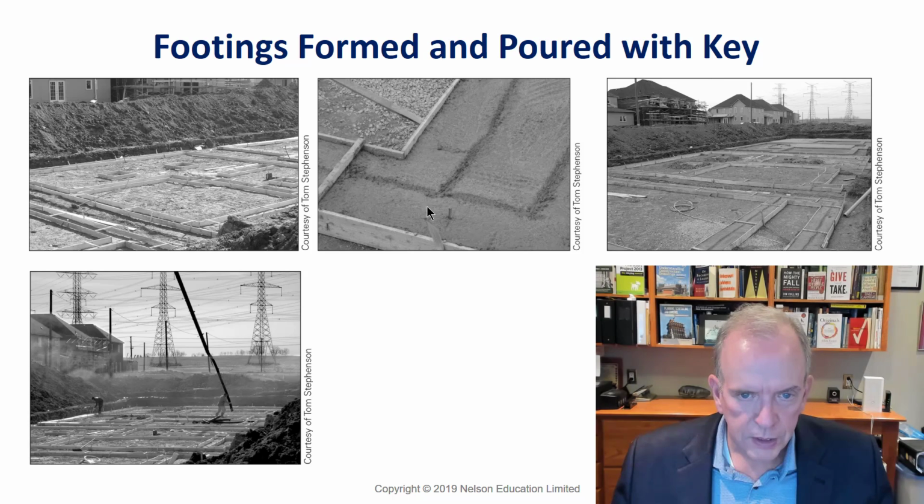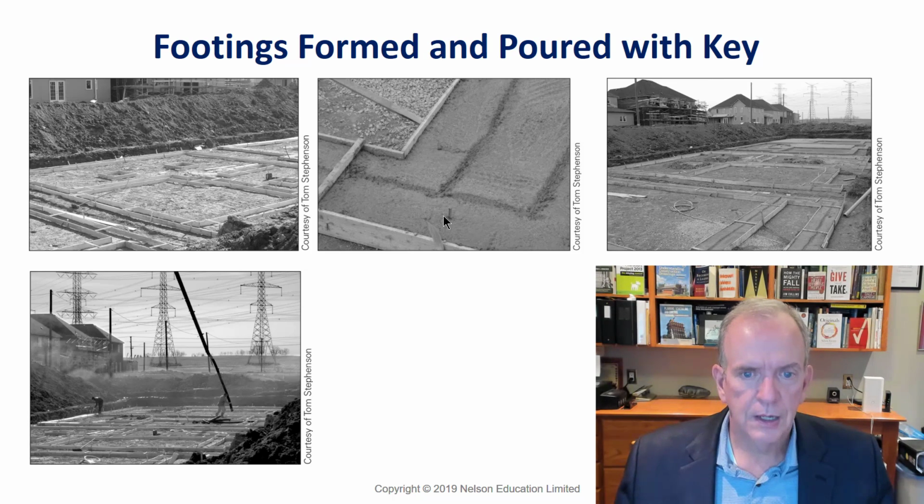And you can remember, I think we mentioned last lecture, the pegs are put into place to show where the forms have to be placed based on the site plan, which is showing the setbacks from the property lines of the site. Usually builders in something like this would get an OLS, an Ontario Land Surveyor, to lay this out.